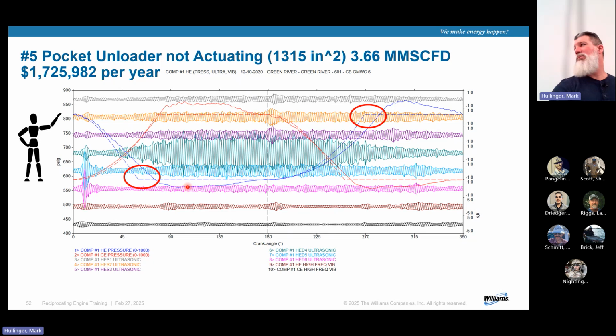So why is that a problem? Yeah, you have a difference in flow, and the PLC is like, well, I don't know, it's broken. I'm going to calculate the flow. Gas control is making decisions off that flow. So the difference in this particular valve was 3.6 million standard cubic feet per day. So the customer thinks they're getting that. Gas control thinks we're flowing that. And if you run the math on that at $2.50, that's $1.7 million per year in lost throughput, just due